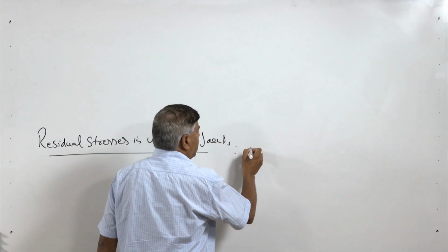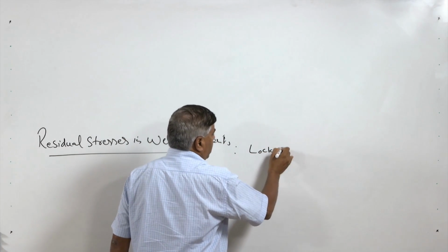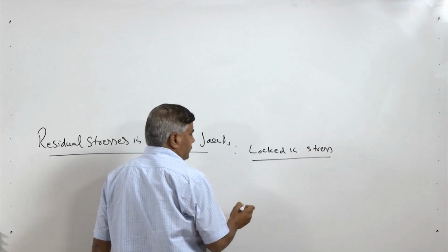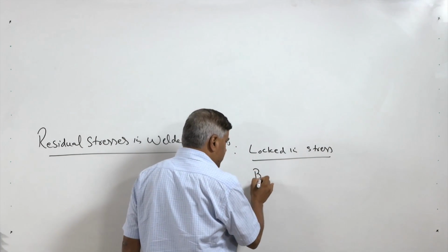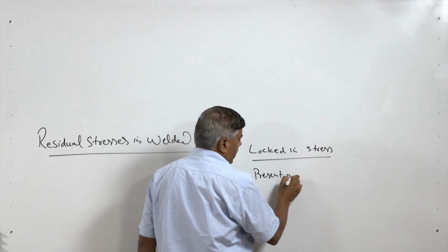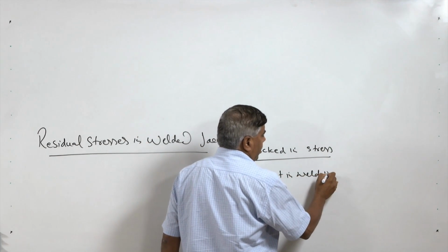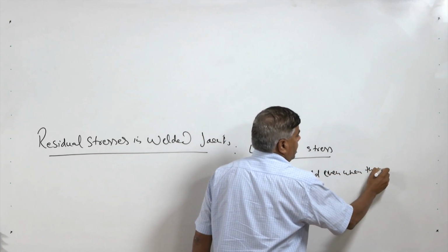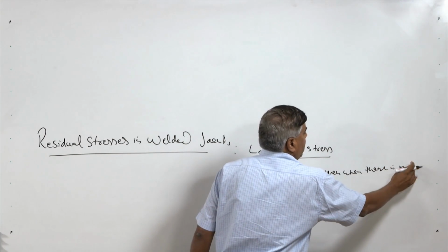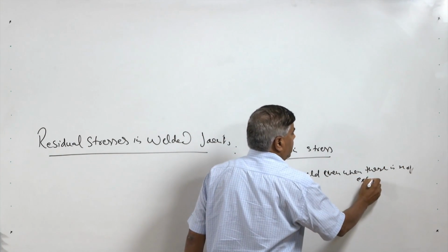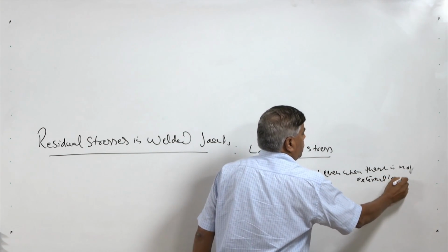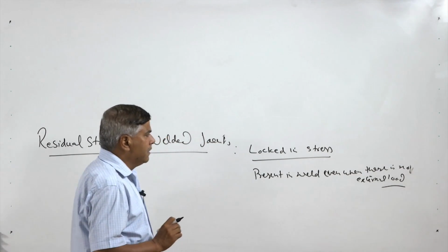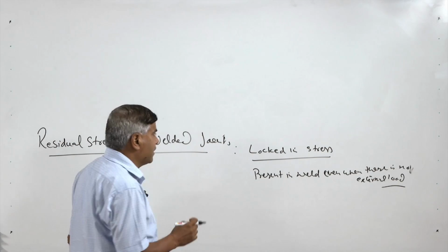Basically, these are locked-in stresses, and these are present in the weld even when there is no external loading. So, these are inherent stresses which are present in the weld without the presence of external loads.